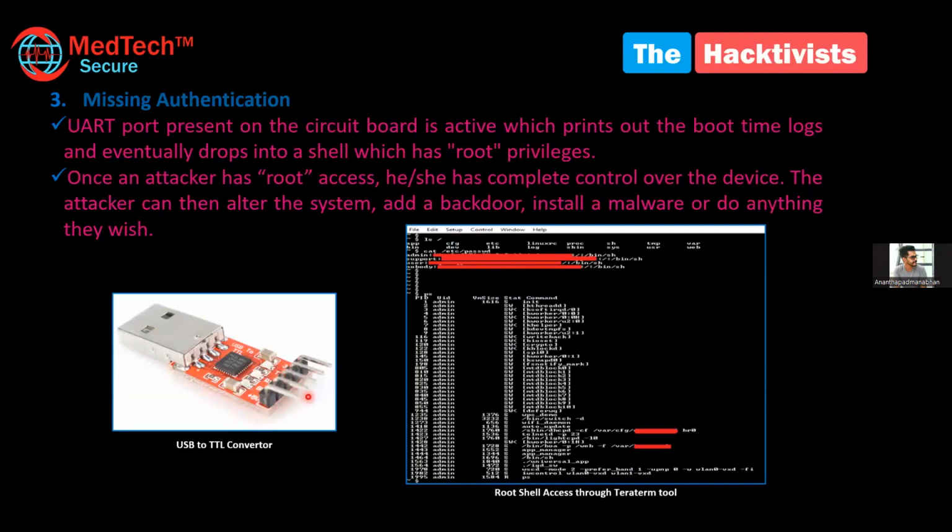So here you can see some pinouts. This will also have a receiver and transmitter. How will the UART communicate with the device? We'll connect the receiver of this device to the transmitter of the UART, and vice versa, the transmitter to the receiver. And we'll use a UI tool called Teraterm for analyzing the data communication.